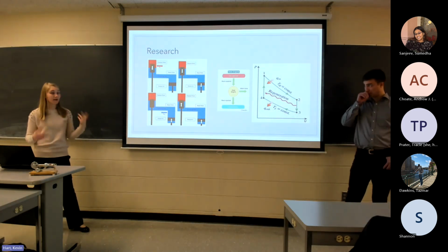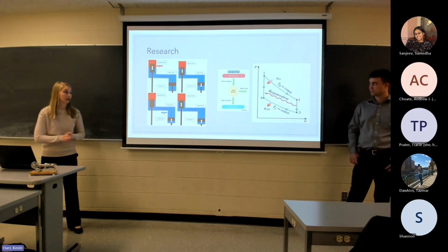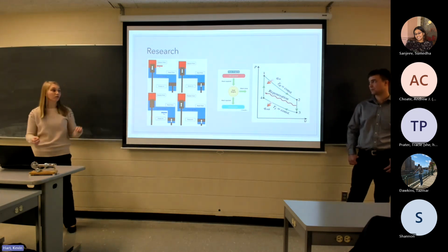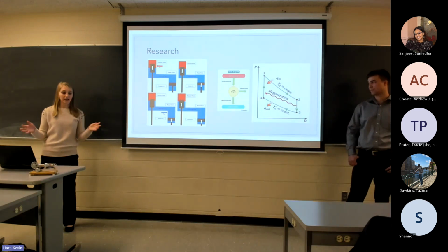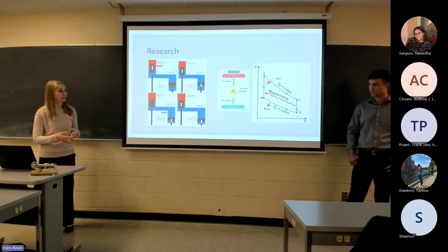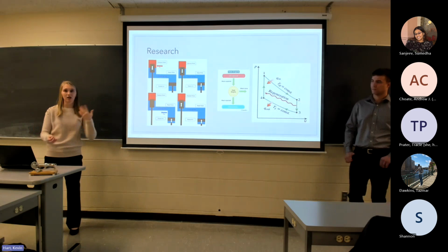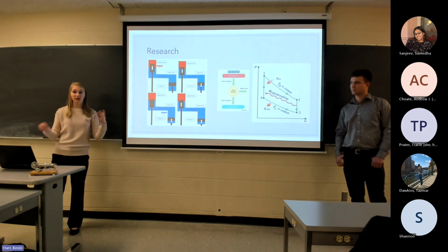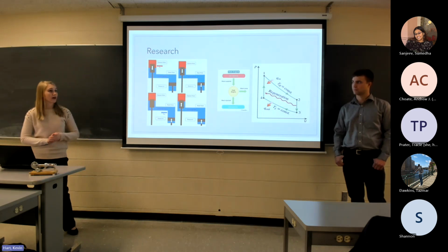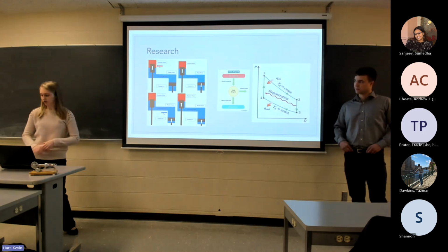And finally, we also have the beta type Stirling engine, which is actually very similar to the gamma type, as you can see here. However, the only difference is that the beta type actually has only one cylinder as opposed to two. So both pistons are in the same cylinder for the beta type, and this actually creates a lower power density. And not to mention, it is much more complicated to build as well. So all in all, we decided to go with the gamma type Stirling engine.